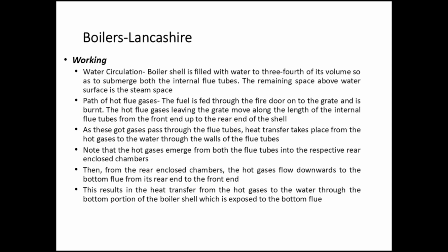Path of hot flue gases. The fuel is fed through the fire door onto the grate and is burnt. The hot flue gases leaving the grate move along the length of the internal flue tubes from the front end up to the rear end of the shell. As these hot gases pass through the flue tubes, heat transfer takes place from the hot gases to the water through the walls of the flue tubes.